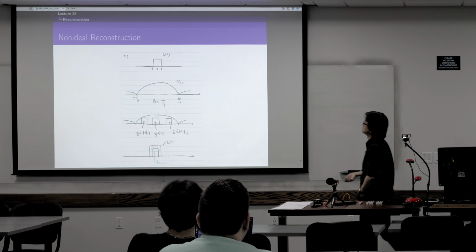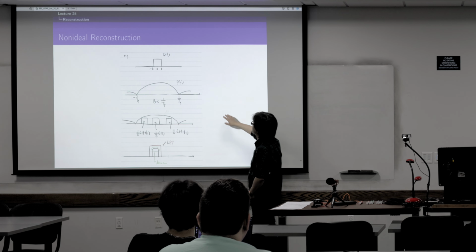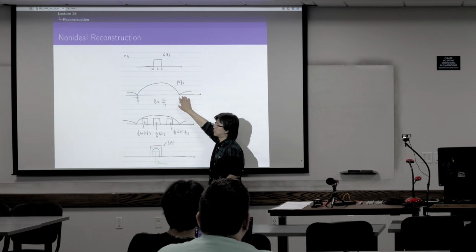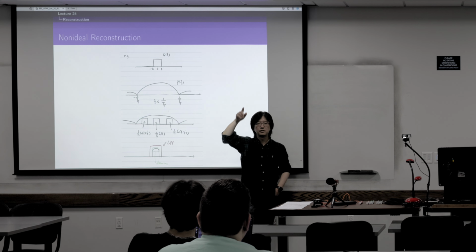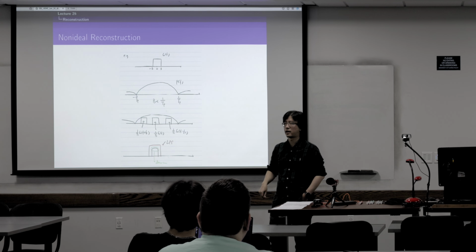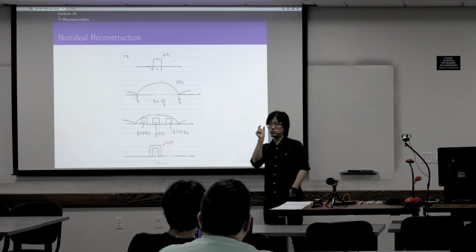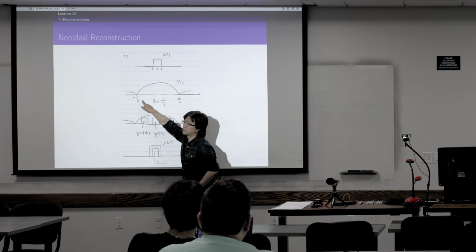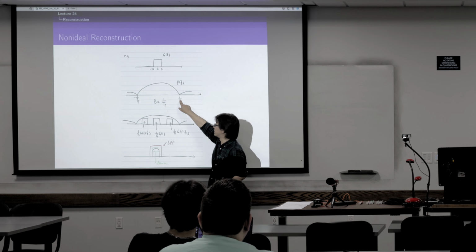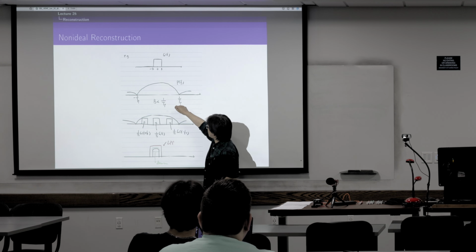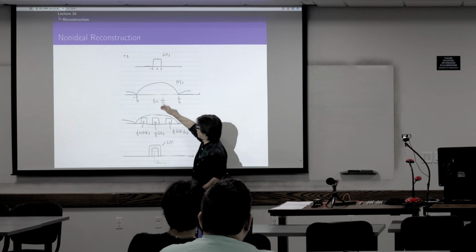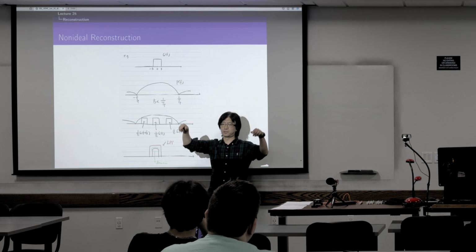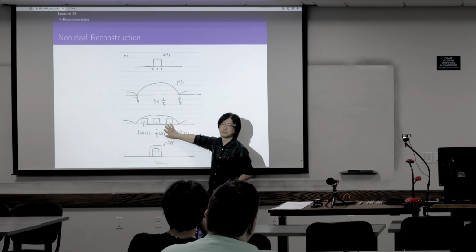The problem is as follows. Basically, let's assume the original signal G(f) looks like that in the frequency domain, and this is P(f), which is a sinc function of the narrow rectangle pulses, right? Because it's narrow in the time domain, in the frequency domain the first side lobe would be very wide, right? It's 1 over TP here, very wide. And then we multiply this with the sample signal, which is a periodic signal. So this is what we got, right?